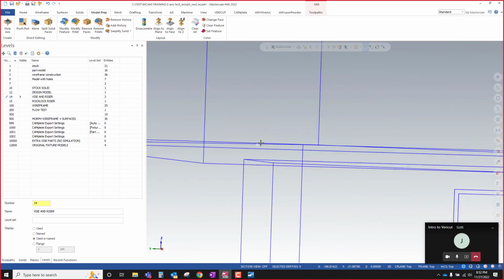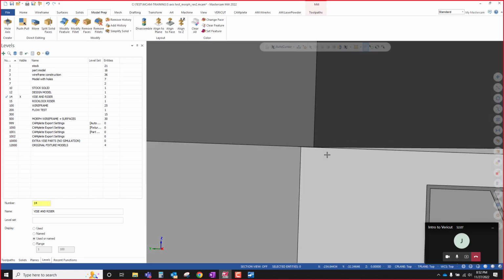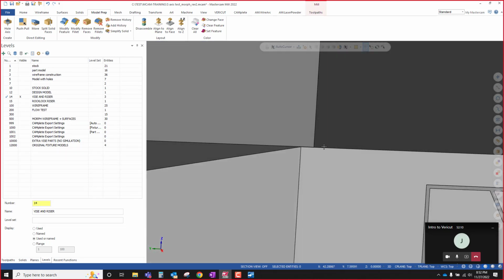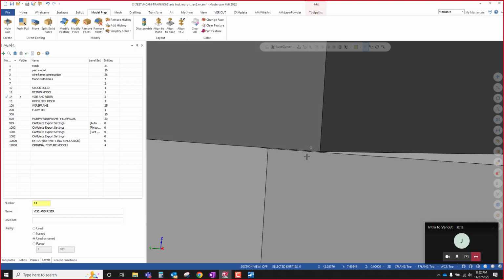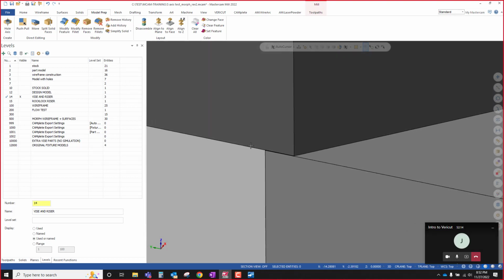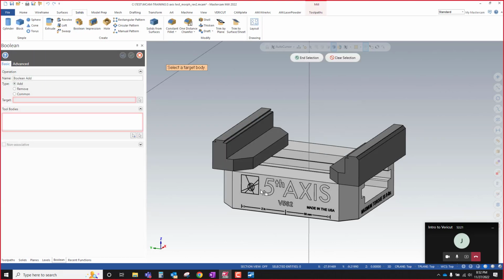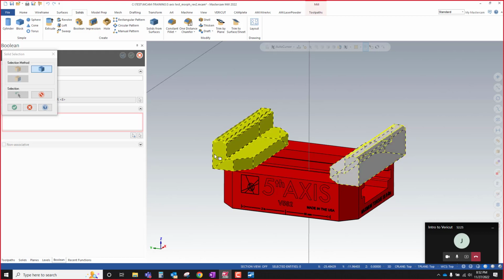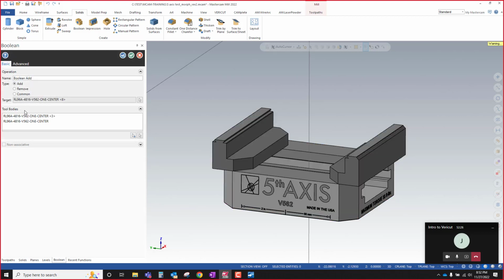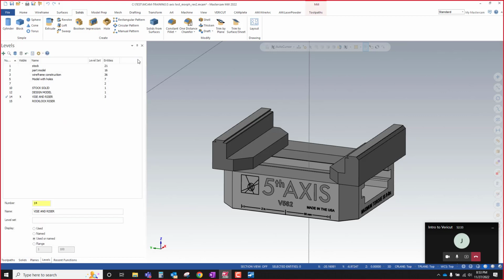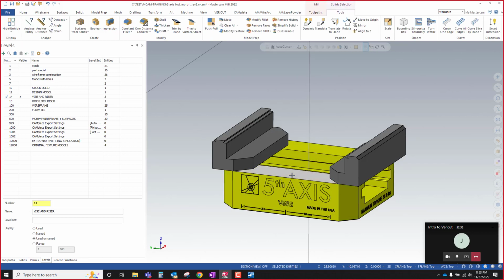And what we have now is these models that should be physically intersecting by at least 4 thou, depending on if there was a gap or not before. So I'll do a Boolean add. So solids, Boolean, and then we'll add this jaw and this jaw. Oh, and I got a warning. Boolean process would result in a disjoint body. Okay, so I have to escape out of there.